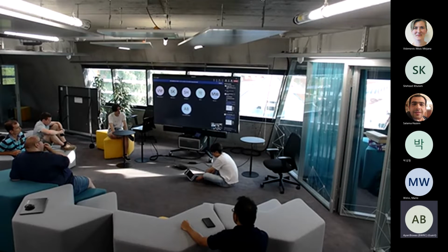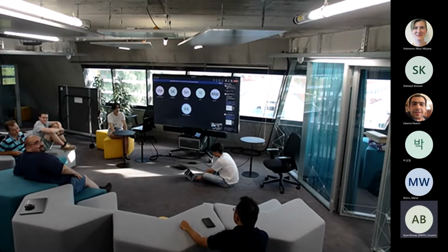Even now, if I want to do a certain design loop, I don't even need to start Virtuoso. Back in BAG 2, one of the main things was you start Virtuoso and load startbag.il into that. That is completely gone now. So we can work completely independently of Virtuoso at the moment, but I think there are certain OA functionalities that are still used in different places, which I will have to test myself. I think you will be able to generate things directly to GDS as well, and then open it up in KLayout or something. But like I said, I think the main concern is compiling the C++.